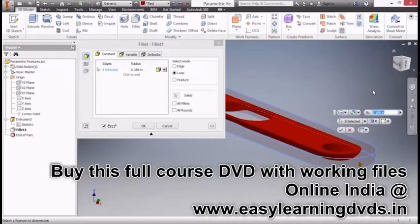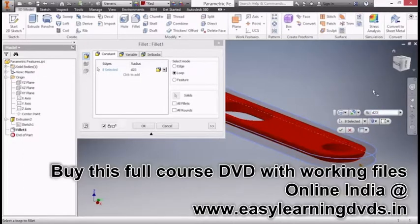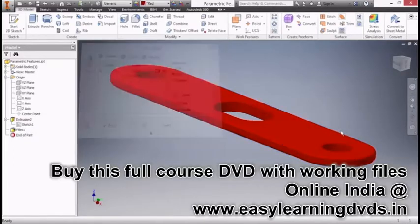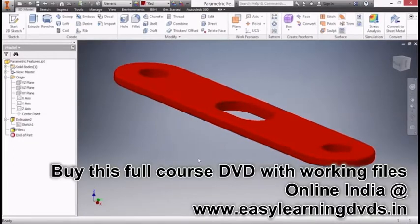I'm going to create a parametric relationship between this fillet radius and the thickness of this plastic piece. Do you remember D23? That was the value of my thickness value for this part. So I'm going to have it equal to D23 divided by 4. So no matter what happens to D23, this radius value will always be that divided by 4. A very simple equation to get your design intent across.